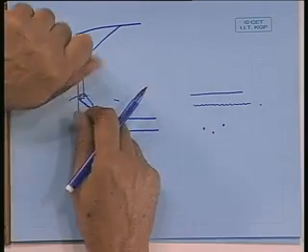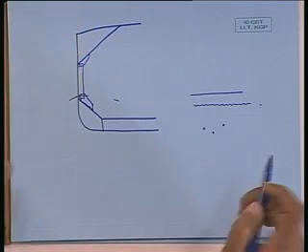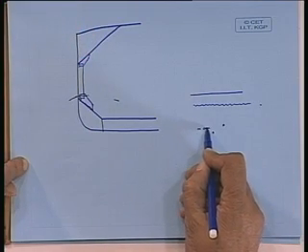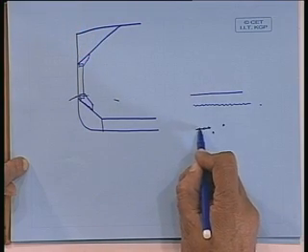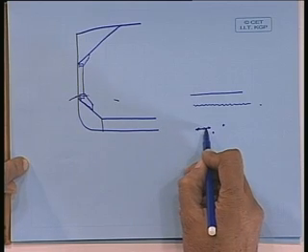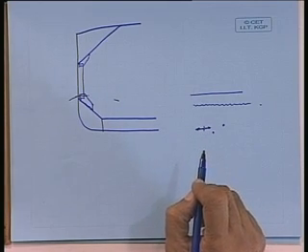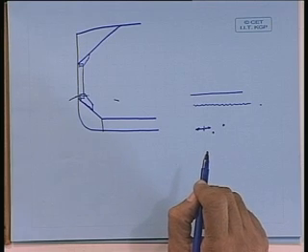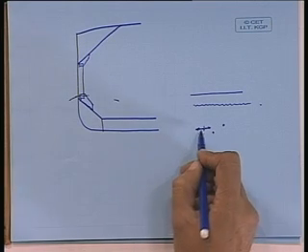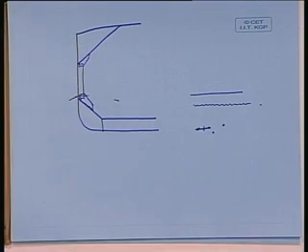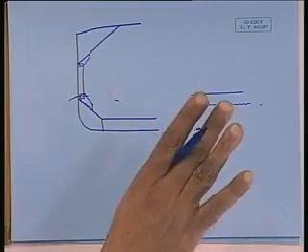and when this thing is subjected to some bending, there is a tension here, and tension means at this part the stress is going to 3 times the surface stress there. It is a small circular hole onto the surface, and on the surface whatever is the fiber stress, you can expect that on this side it is 3 times of that.